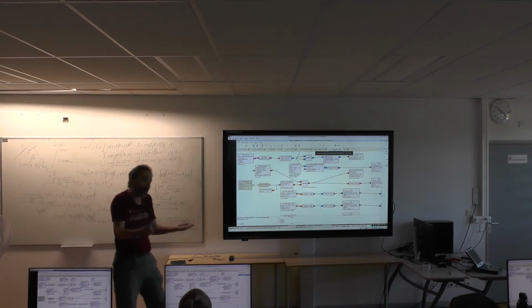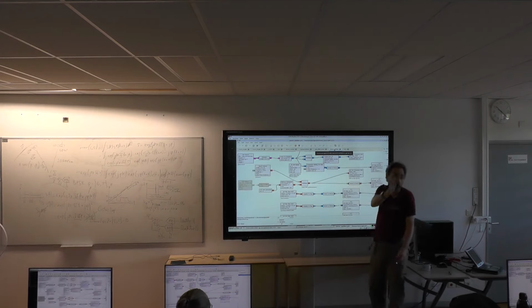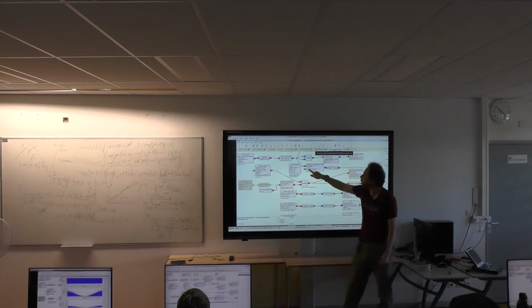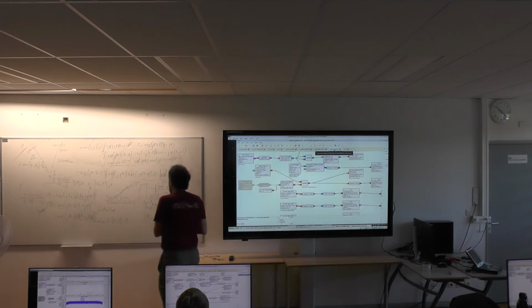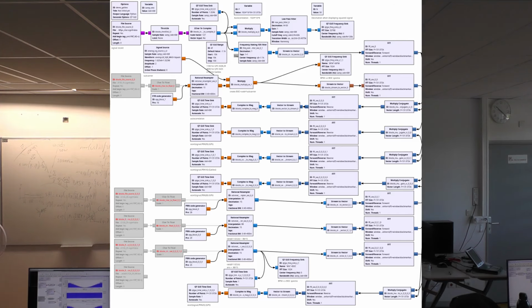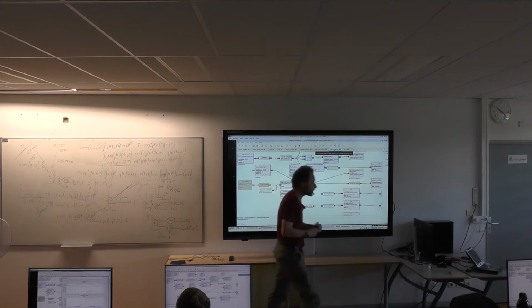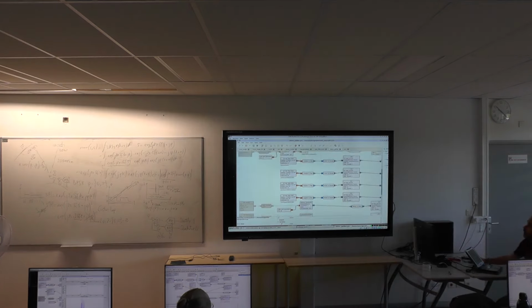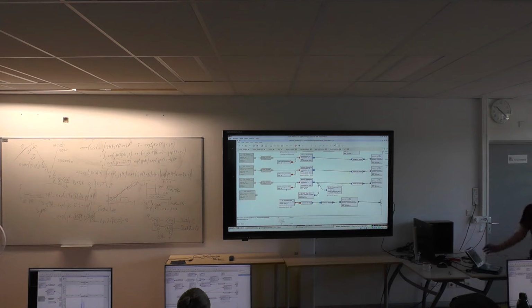Well, we need to run the correlation against each satellite pseudo-random sequence for various frequency offsets. And how do you introduce a frequency offset? In GNU Radio, you take the signal and you run it through a frequency translating Fourier filter. So frequency translation is a software implementation of the multiplication with a local oscillator, and you get a frequency transposed signal. So we take the signal, we convert it to floating point numbers, we shift it in frequency, and then we run correlation with all the copies of the codes of a signal that might be there.